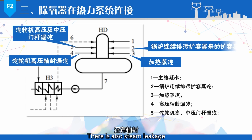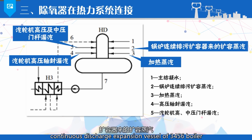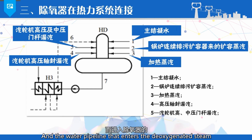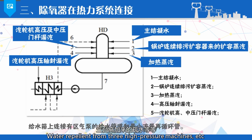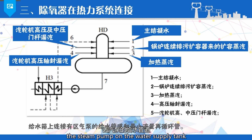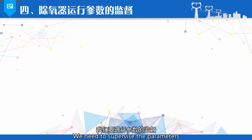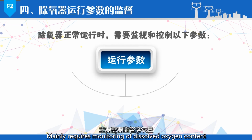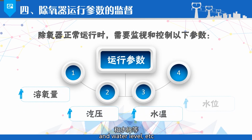There is also steam leakage from the shaft seal door rod, and expansion steam from the continuous discharge expansion vessel of boilers 3, 4, 5, 6. And the water pipeline that enters the deaerator has condensate water, drain water from high-pressure heaters, etc. The water supply pipeline is connected to the steam pump on the water supply tank and the minimum flow recirculation pipe. So when the deaerator is running, we need to supervise the parameters. Mainly requires monitoring of dissolved oxygen content, steam pressure, water temperature, and water level, etc.